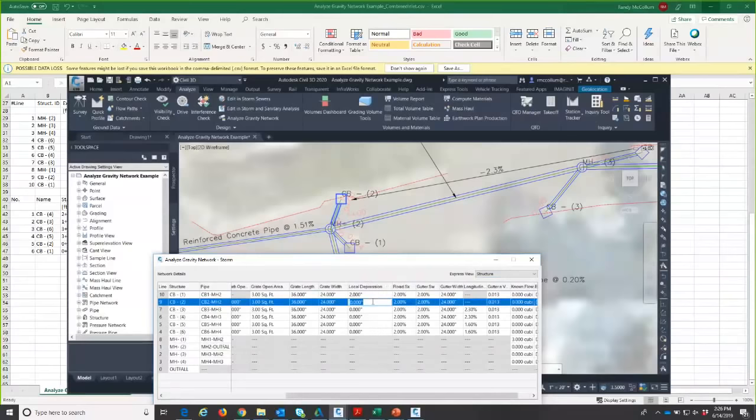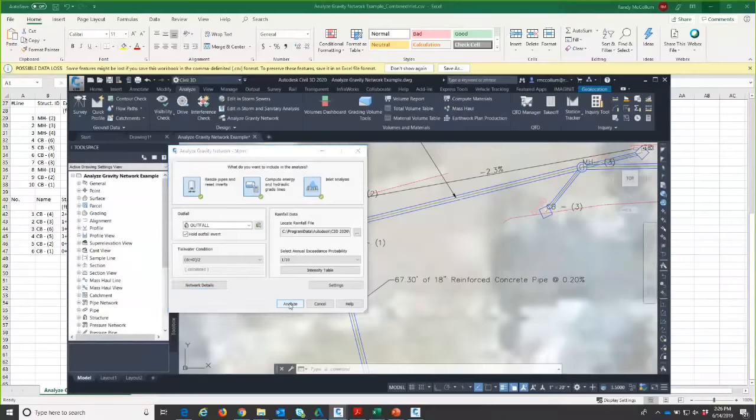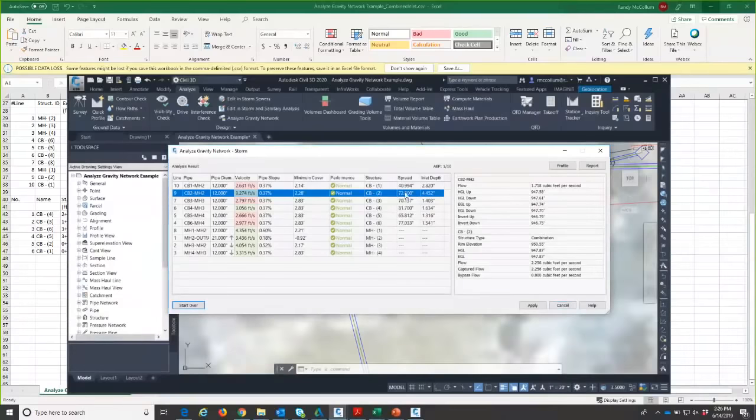And in this case, I found 2 inches was okay, but a 3-inch depression. It looks like it's on an inset curb, so that should be fine. I'll just change that value, and then we'll run it again. And that spread I can live with.